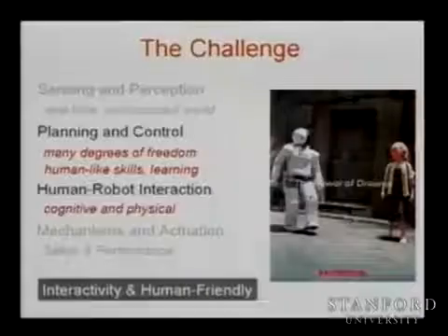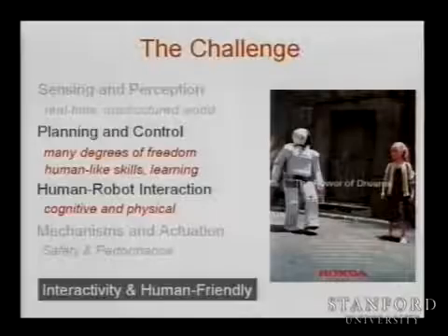Yes? The sensors are in the joint or at the extremity or both? Well, there are sensors on the inside of the structure to measure tension on the muscles, but also we have sensors distributed on the skin outside, and that will measure contact with the environment. So when you hit first, you dampen, so you reduce the impact force, and also you measure where you are touching.